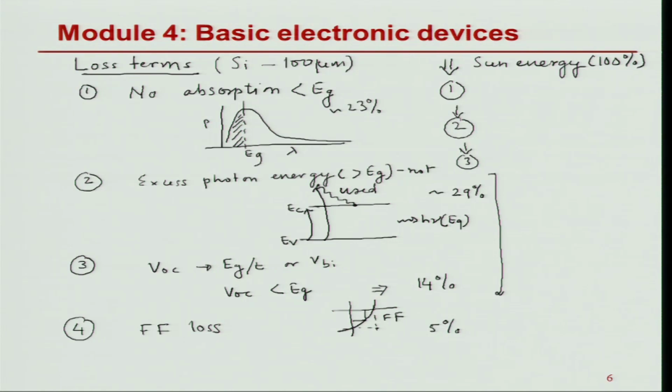And this is just from a typical PN junction that I have just calculated assuming ideal values. This is a loss that I am going to see. So, this is my theoretical PN junction efficiency for a silicon device, and for a single junction, it comes to about 29%.